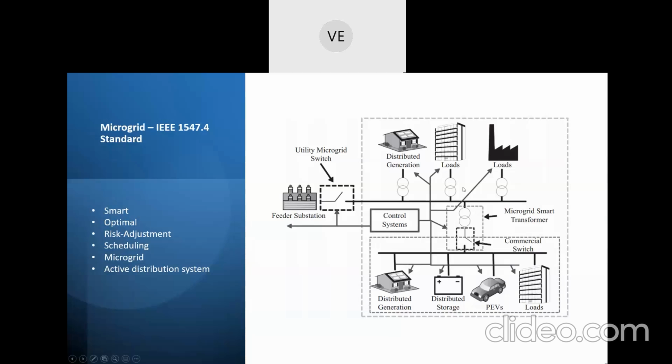Now, what's the challenge of scheduling? Because we completely depend on the forecast, but in the actual time horizon, it may deviate from the forecast. So the actual output may be different according to the real-time solar radiance from the PV modules, the real-time wind velocity, and the real-time state of charge available in the EV batteries.